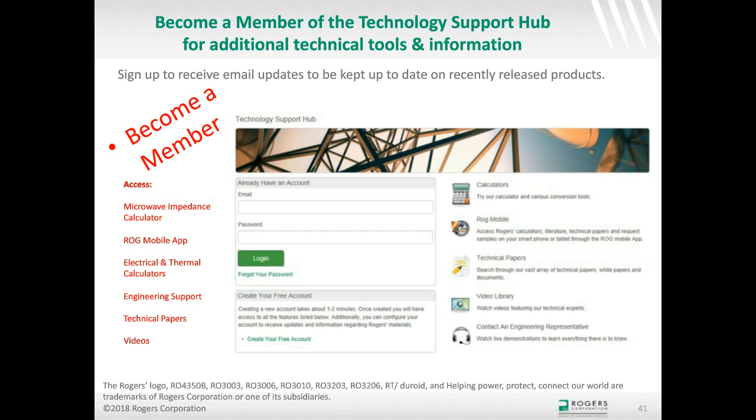Yeah, that's a good one. And it really depends on those different dependencies. So if it's a very thin circuit and the copper's rough, there's going to be a pretty big difference between the bulk Dk of the material and the Dk as the circuit would perceive it. If it's a thin circuit and the copper is very smooth, then that doesn't slow the wave velocity much. And that means the dielectric constant of the circuit and the bulk dielectric constant are not going to be that different. So it really depends on the circuit construction. Thin is going to have a bigger influence due to the copper surface roughness, and it's going to be a different number in a thin circuit than a thicker circuit. On a thicker circuit, where the copper is farther apart, the difference between the bulk Dk and the Dk as the circuit would perceive it is going to be pretty close to the same, to be honest.